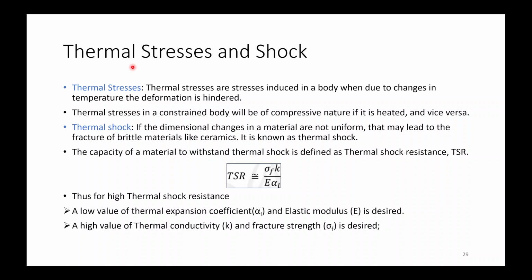Now thermal stresses and shock. So thermal stresses are stresses induced in a body when, due to changes in the temperature, the deformation is hindered, and thermal stresses in a constrained body will be compressive in nature if it is heated and vice versa.